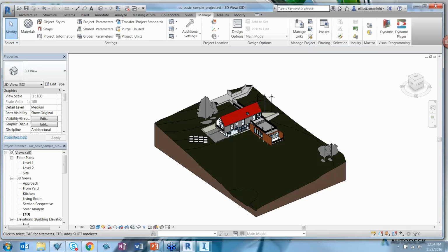Great, thanks. Yeah, and that's a perfect segue. The next question I was going to address is, do I need to have the same version of Navisworks if my model is made by Revit 2017? You do need to have Navisworks and Infoworks 360 aligned. Unfortunately, I'm not sure if you need to have Navisworks and Revit aligned, but if you're going to be using Infoworks 360 2017, especially for a locally imported operation, you're going to want to have Navisworks 2017 installed.